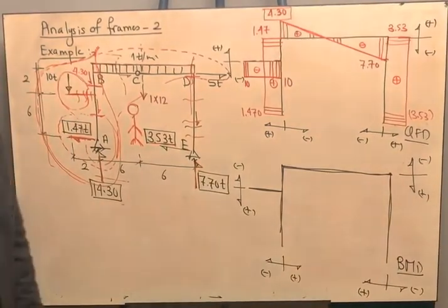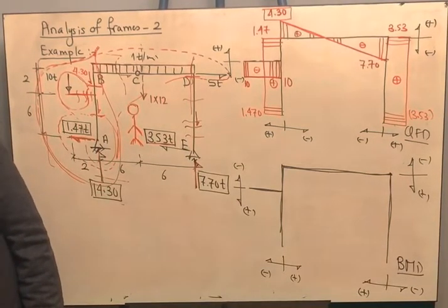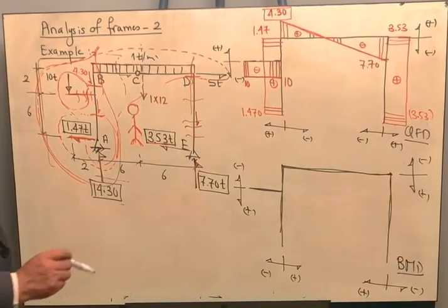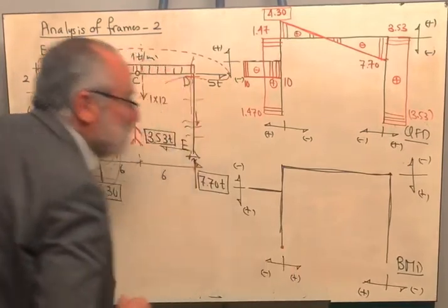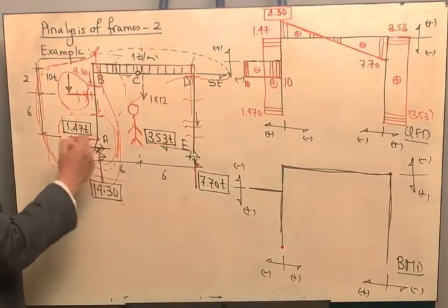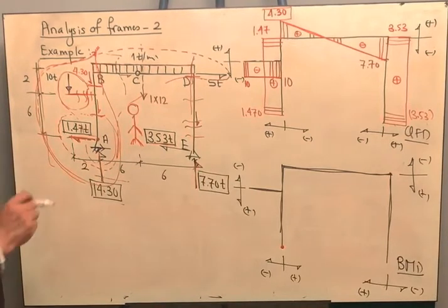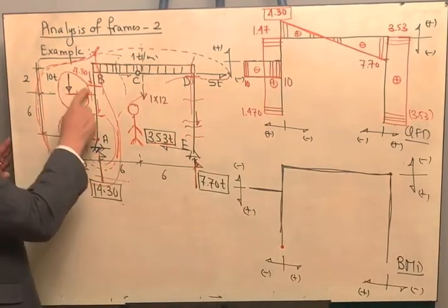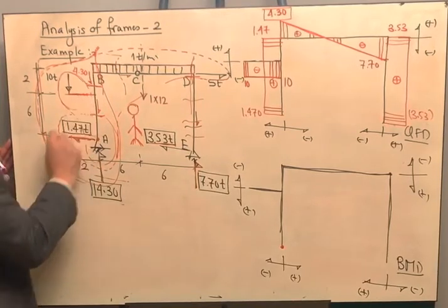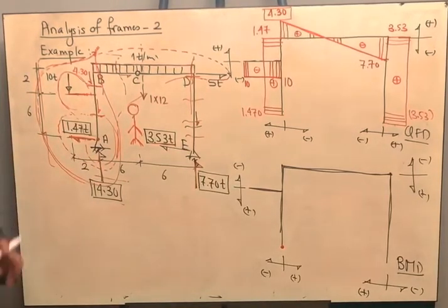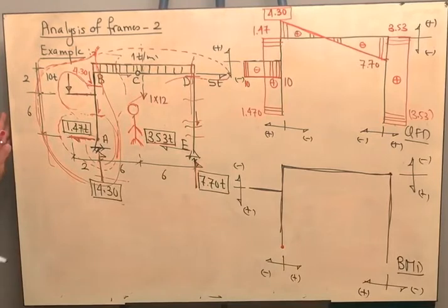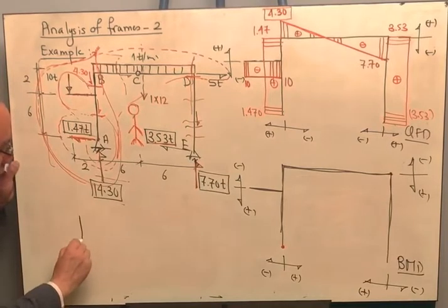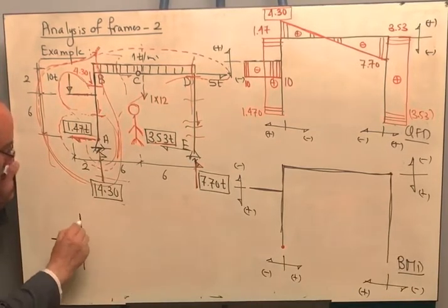Very good. Okay. The magnitude of the bending moment at point A is equal to 0. Because when you are cutting a section here, all of the forces are passing through point A, so I don't have bending moment. This point where the cantilever meets with the column of the frame, basically it is 3 points. I would advise that you draw the free body diagram of that point. If I will have to draw this intersection like that.